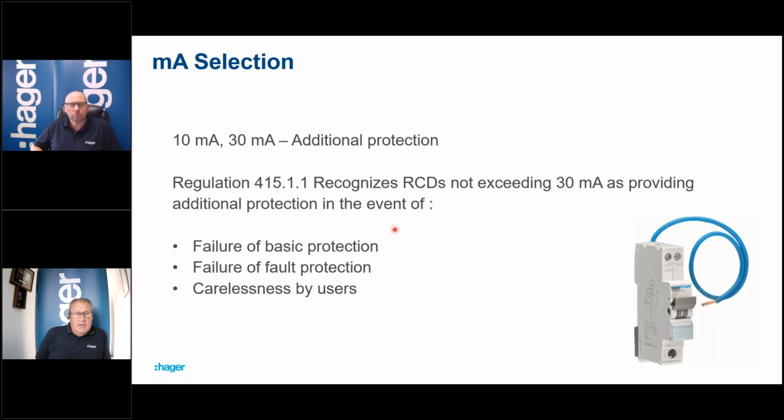Now I'm going to pass back to Paul for this one to talk about some regulations about where they're used and different types of milliamps. Thanks, Paul. Yeah, so I think most people are familiar with 30 milliamp devices as being used for additional protection, but of course there are devices out there with a smaller trigger rating.